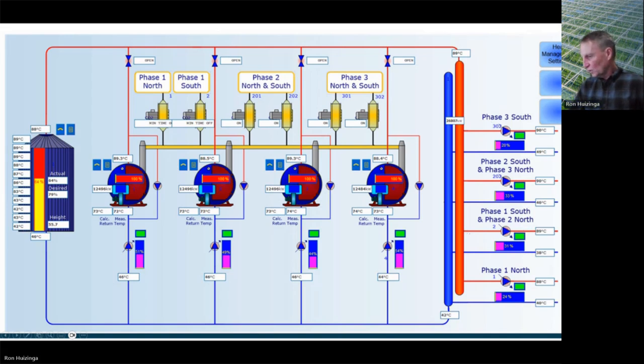So basically what we do is we look at these return temperatures and we calculate the last 2 sensors in the tank. Whatever temperature they are, that's going to be our empty temperature. So that's going to be 42, 43. When all these sensors read 42, 43, that's going to be our empty. But the next time it fills up and empties again, if these are at 46, then they all have to get to 46 for the tank to be empty.